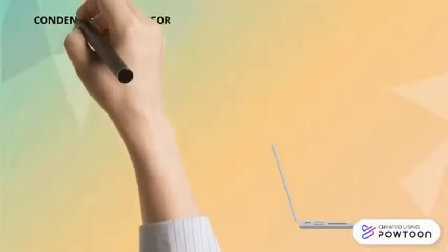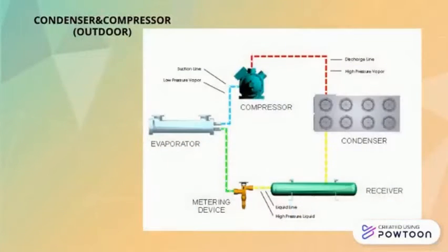First, the outdoor unit, the condenser and compressor. The condenser takes hot gaseous vapor coming from the compressor and cools it back into a liquid form. The compressor pumps refrigerant through the aircon system. Refrigerant is the fluid that absorbs heat from inside the building and carries it outside.